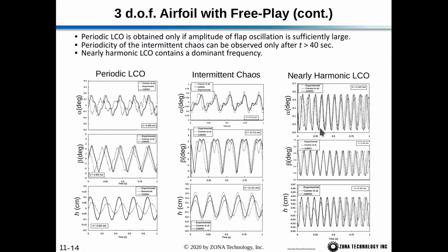And then finally, the nearly harmonic LCO is a higher frequency. So our angle of attack, our flap rotation angle, and then our plunge. You can see that the plunge amplitude is much smaller as compared to the intermittent chaos and the periodic LCO.